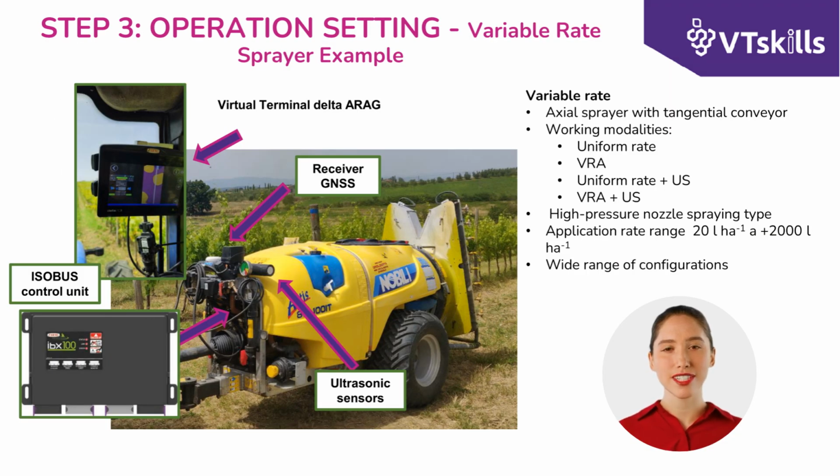The optimization of plant protection products today is also achieved with variable rate sprayers. These machines are equipped with 4 main elements to differentiate the application of the crop protection mixture: a satellite receiver that indicates the correct position, an onboard terminal that consists of a control actuation unit, an electrical and data connection to the sprayer called ISOBUS, and a spray automation system based on adaptive dispensing solenoid valves.